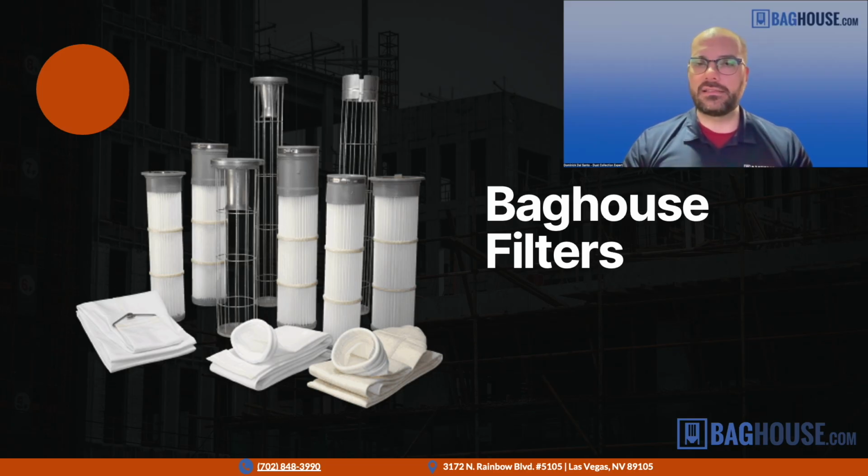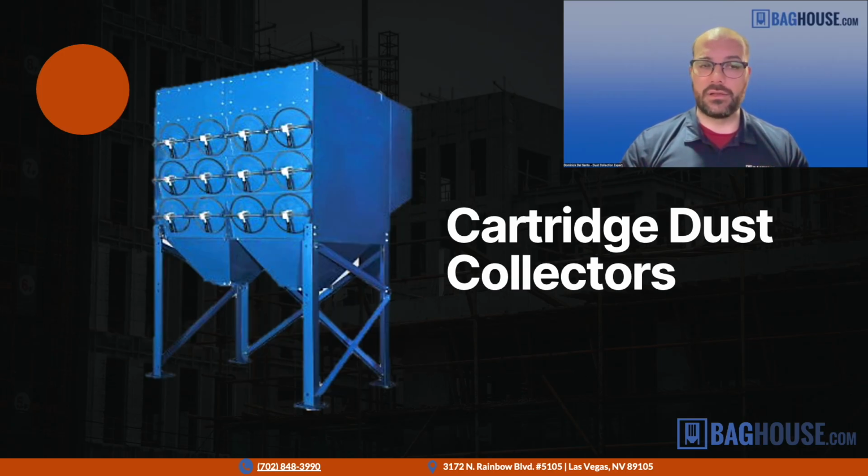And if you see in the slide here, what you're seeing is a mix of bags that are folded, the wire cages that support them, and then next to those, you see pleated filter elements. These are a special kind of filter that we can put in our baghouse. We'll come back to that in a sec. First, let's go to the next kind of dust collector that we often see, which is cartridge collector.